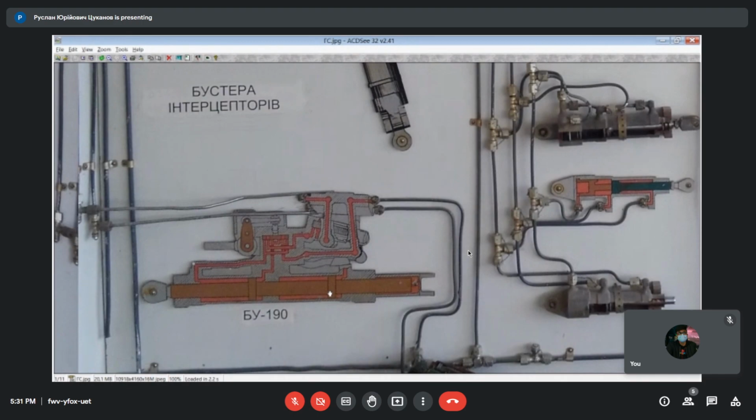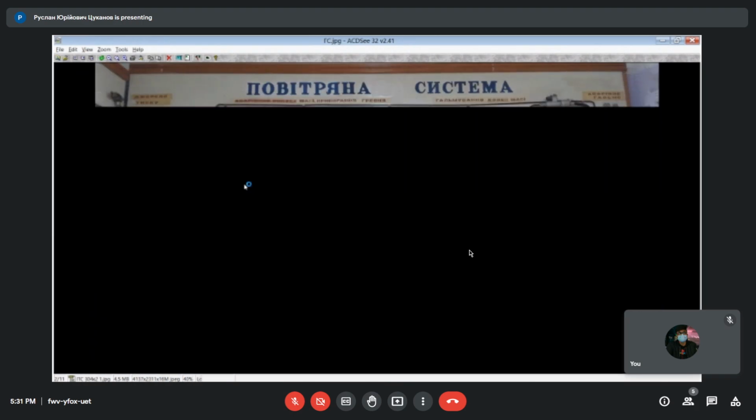Each wing will include a similar but a little bit lower size tandem type actuator, which is used to control spoilers. In this case, these are spoilers intended for roll control. It's not only ground spoilers. So they have feedback like a stabilizer and provide differential control, of course, for roll to the left or to the right.